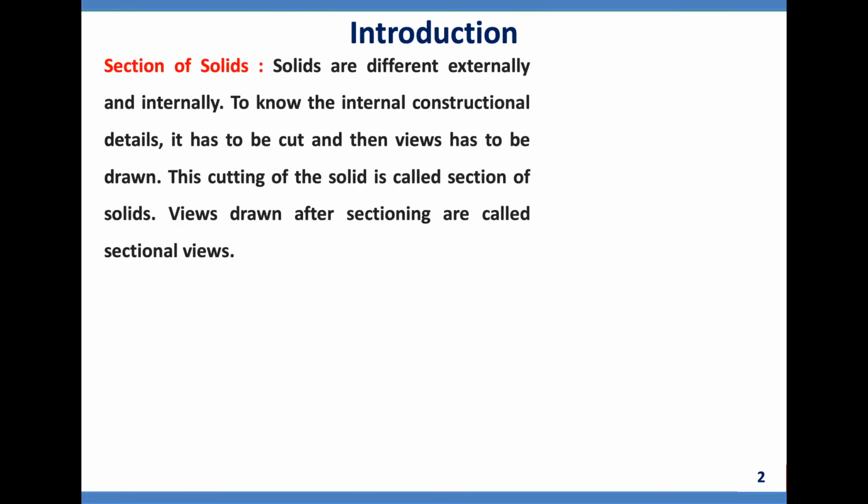Section of solids. Solids are different externally and internally. To know the internal constructional details, it has to be cut and then views have to be drawn. This cutting of the solid is called section of solids. Views drawn after sectioning are called sectional views.